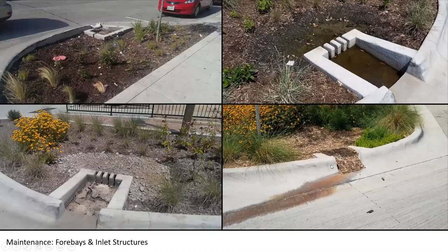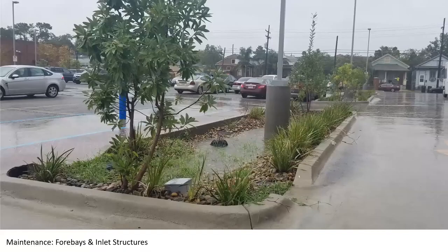I'm not a big fan of just these concrete forebays, especially the open ones, because typically if it doesn't have a lot of free drainage, like if your landscape isn't below where the water comes out of these inverts or these structures, you'll end up getting ponding water and a lot of muck and debris. So you can also just, if you want to, do a rock forebay.